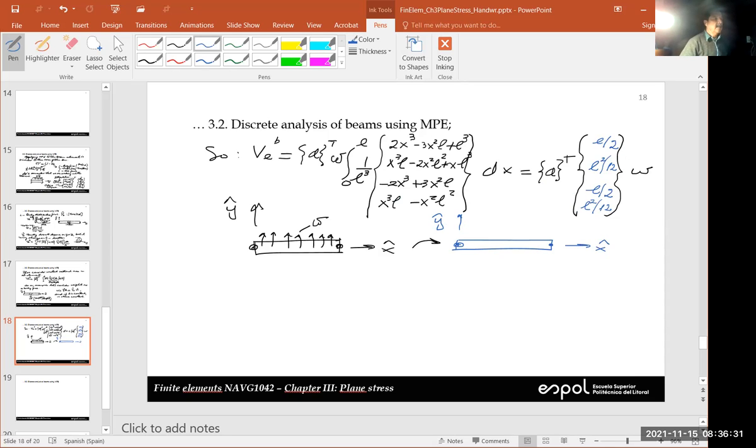So what we're saying is that if we had one case in which this is uniform, remember this is force per unit volume. Now, if you multiply by the area, you get force or weight per unit length. So this you convert into the total forces, and you convert that into half here and half here. So this is WL over 2, WL over 2. Since this is a total weight divided by 2, makes sense.